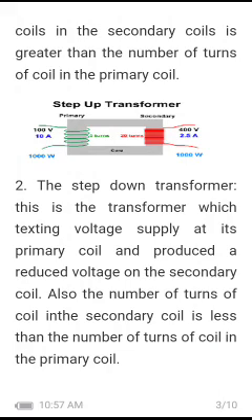Look at the primary coil, the green one inside that metal. There are 5 turns. For the secondary coil in red color, we have 20 turns. We have 400 volts and we have 2.5 ampere. The same 1,000 watts.